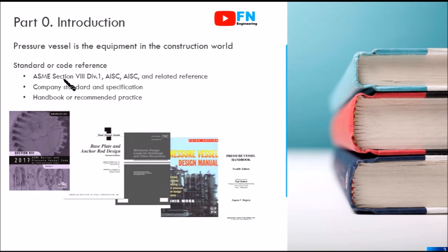A little about the difference between ASME stamp and ASME code. The main difference is that an ASME stamp product requires an ASME authorized inspector during calculation and drawing, material purchase, fabrication, and testing of the equipment. So, the ASME stamp product has to have an ASME nameplate. It is commonly called the U-stamp nameplate.